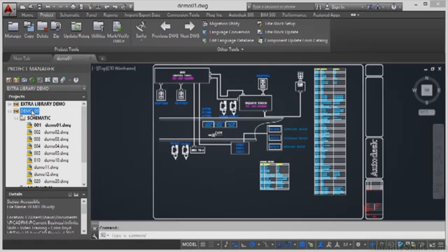And what I do now is I select Demo 09, right click, activate, and make that the current AutoCAD Electrical project. Now you won't find Project 002 in your working files. It was just put there purely as a test to show you how the delete project works. But that's how you delete projects in AutoCAD Electrical. And remember, when you delete a project, it is permanent. It's gone for good. You'll never get it back.